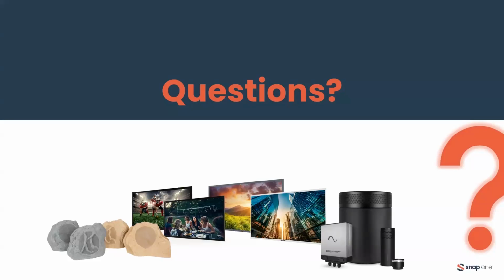Is there any delay in long runs or speakers placed far from the amp? Great question. The short answer is no. The long answer, I would say, is if you're talking about the distance from the amp to the speaker, or the set of speakers, the answer is no. But if you're talking about large runs and distances between speakers, then yes. Typically, for every 1 foot you travel, you get a delay of about a millisecond. That's just the speed of sound travel. And so what you will start to hear in really large systems is the echo effect of speakers that are far away. So the short answer is no, you don't get any signal delay through the wire for long wire runs.